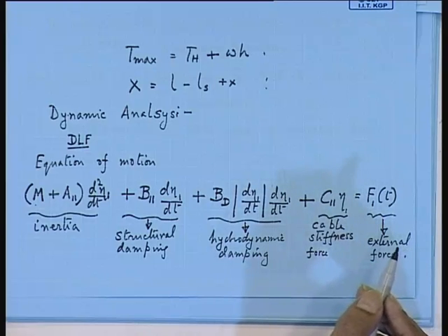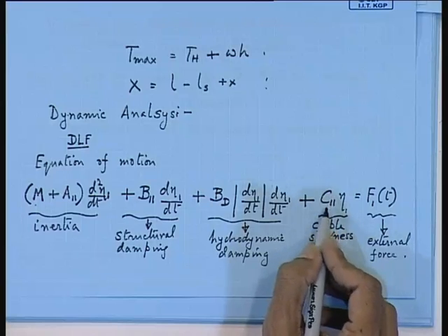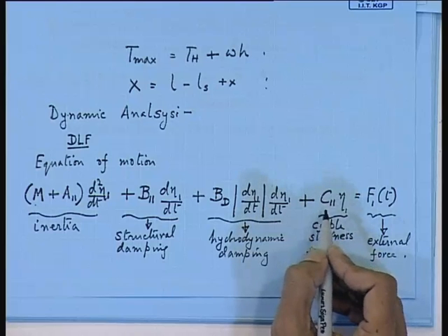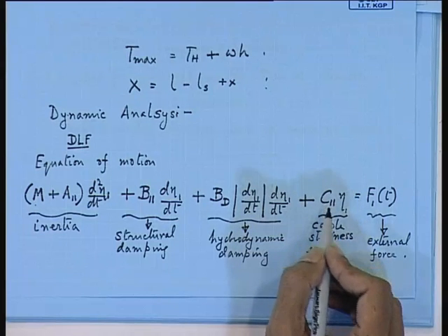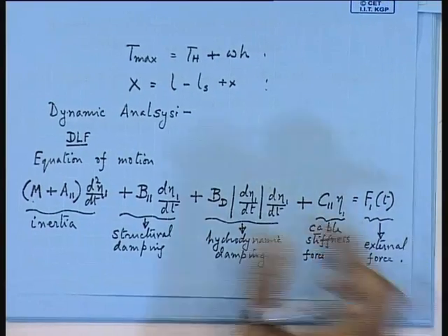Now, which one is the easiest? Easiest is the variation if you can vary this C11, because mass and added mass is very difficult to change. So, stiffness you change by changing your cable tension. So, normally this is what we will come across in TLP also, the cable tension they change in order to avoid the resonance. Both you change, the frequency, and also your excursion, that is the amplitude of vibration. So, both are equally important. Why?